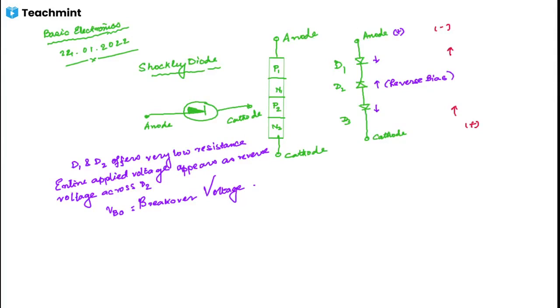The reverse current flowing through them would rise rapidly and the heat produced by this current flow could ruin the entire device. For this reason, Shockley diodes should never be operated with a reverse voltage sufficient to reach the reverse voltage breakdown point.